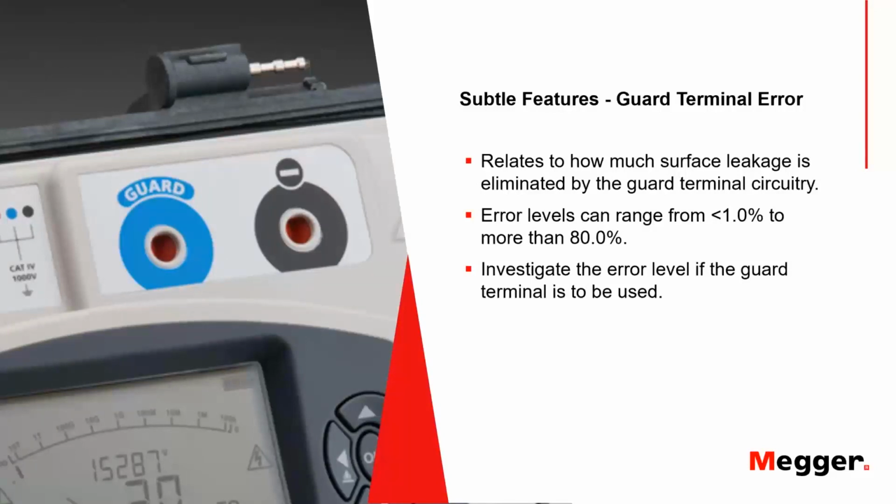Guard terminal, this is one of the areas where a poorly designed tester that's trying to go to market on a low price, one thing that the engineering can cut is your guard terminal quality. They can say, oh yeah, we have a guard terminal. But remember, when you engage the guard terminal, it has a plus minus accuracy just like your plus and minus terminals do, but that accuracy is added on to your basic accuracy.